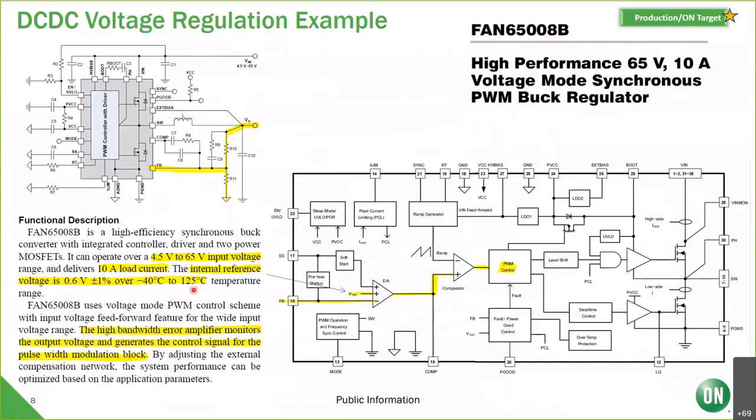So that's part of what we provide. This circuit is trimmed at the factory at wafer fab, at wafer sort, to be able to display that kind of accuracy over time, over process and temperature. That goes into a comparator with the ramp on the other leg of the comparator, and that develops the PWM, or pulse width modulation control, which gets level shifted and sent out and controls the high side and low side FETs.